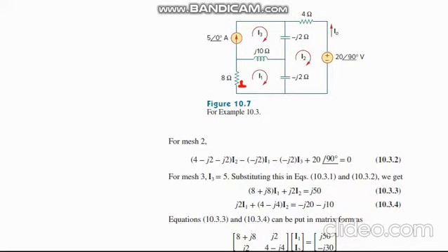you have to give the polarity. Analyzing the first loop, that is I1, the current enters in this direction. The entering direction will give the plus polarity, and the outgoing side will be negatively polarized. And then again plus, minus: incoming current plus, outgoing current minus.